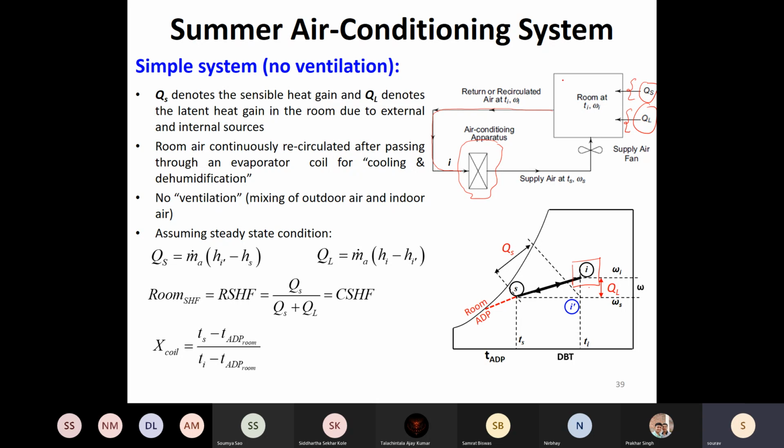What it means is, if someone is looking at maintaining 16 degrees C inside the room and someone else is looking at maintaining 25 degrees C inside the room, the 16 degrees C fellow will actually see larger heat leak from outside, which is let's say at 40 degrees C. Even if you just look at the conduction heat transfer across the wall, kA dT, this dT is higher for this fellow.